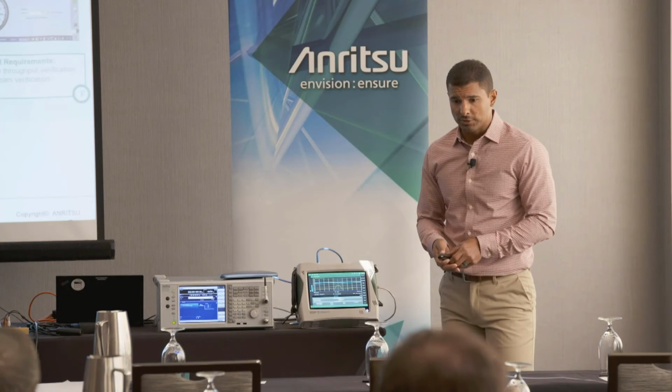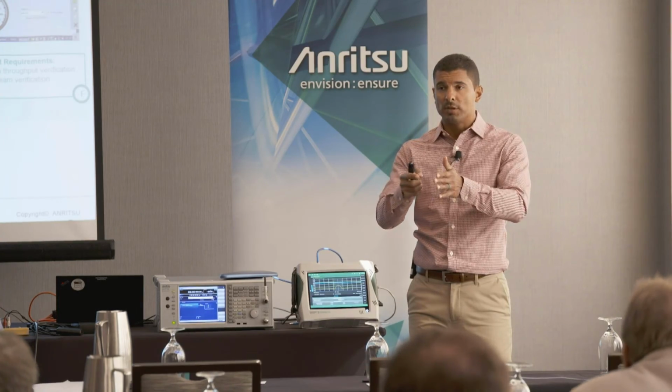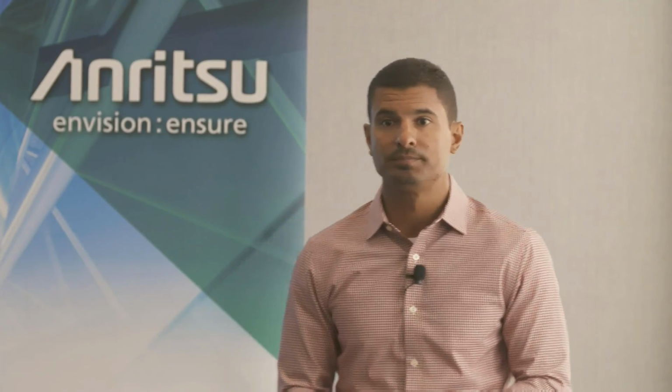As we go through the presentations, you're going to see that as we move from 4G to 5G, we're going to go away from CPRI and go more into a packet-based transport. Once we move to packet-based transport, we get the flexibility to start differentiating individual services based on their different requirements that I showed in the previous slides, latency requirements, synchronization requirements. Moving forward, Jeff and I are going to discuss how those changes are affecting over-the-air measurements and how we do them today, as well as how we do the transport and optical measurements over the network. All right?